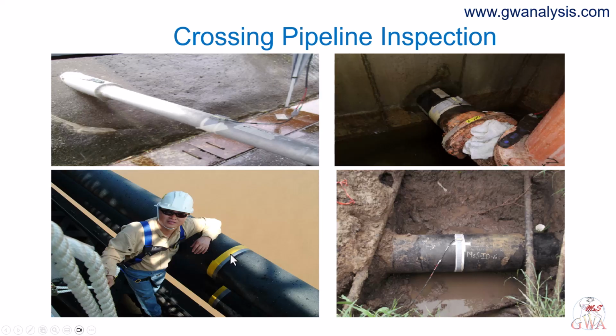I want to say plainly why we spend so much time on coupling in this training. The waves have to get from the transducer to the pipe wall and back again. And it does that through the coupling. Everything downstream of bad coupling is worthless. The range, the sensitivity, the threshold, the report. No amount of gain fixes it, and no amount of analysis recovers it.